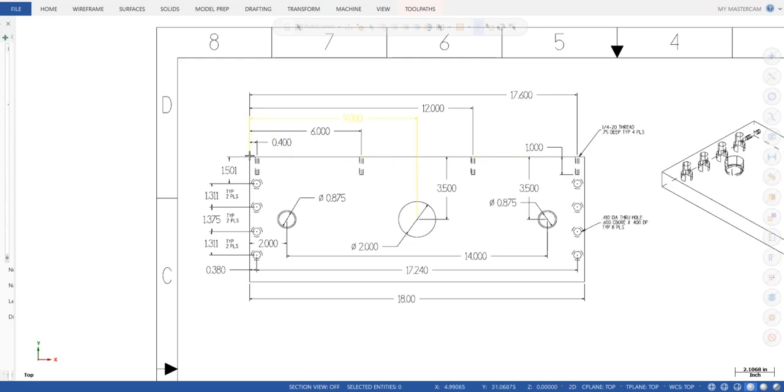So the intersection right here I would definitely call x0, y0, because if I am drilling a hole, then I will actually see an x value of 380 right here, and then minus 501 for this first hole. Okay, so that allows you to verify the location of that hole based on the dimensions that you see on the print. It makes it very simple to troubleshoot or to verify that your locations are correct.